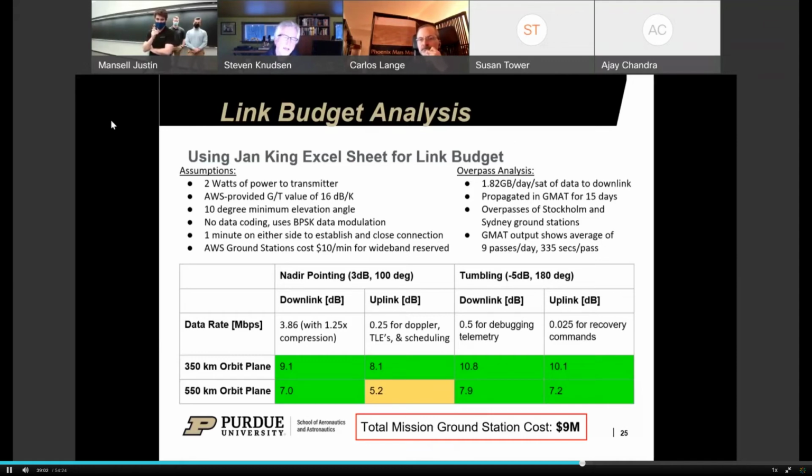I guess. I've done quite a bit of radio work, and I would be marginally comfortable at 10 dB, given atmospheric conditions and things like that. In the past few years, we've seen, for example, a lot of smoke coverage and a lot of storm coverage that would really harm your link margin there. So I know that you've got it unencoded with BPSK. Did you consider doing anything a little more complicated to see if you could increase that link margin?